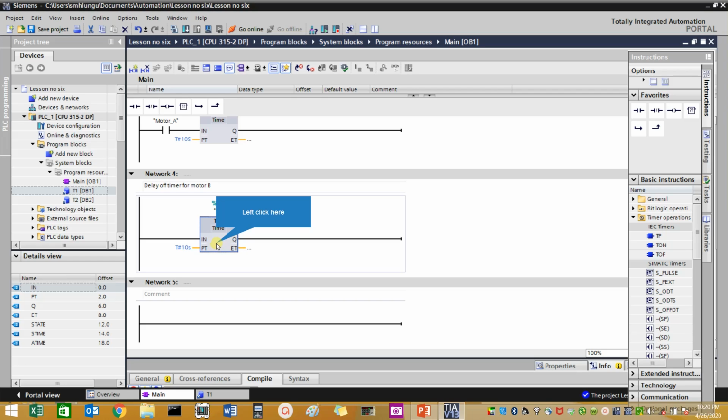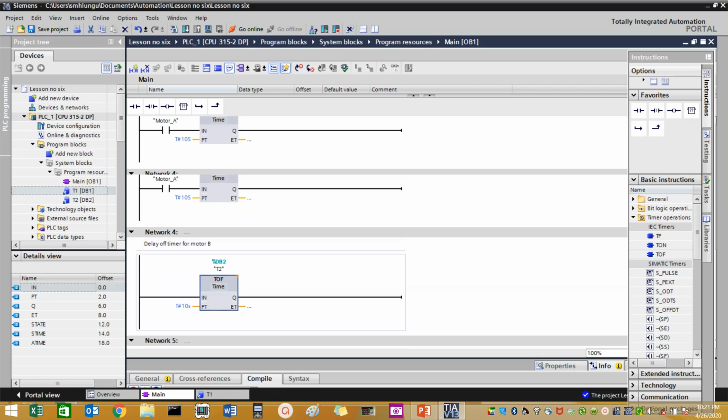As soon as you energize a relay for this particular timer, the contacts will change immediately. Let me repeat that. A delay off timer works like this. As soon as you energize the coil of this relay, a delay off timer, the contacts will change immediately. So they will change their states.